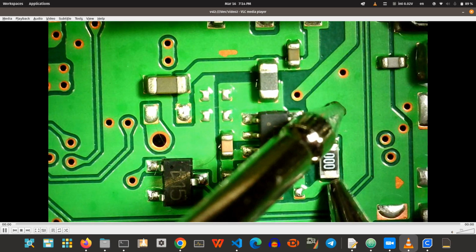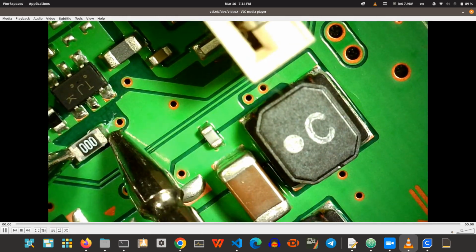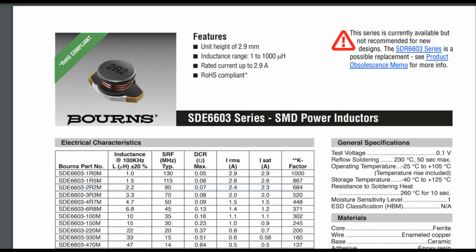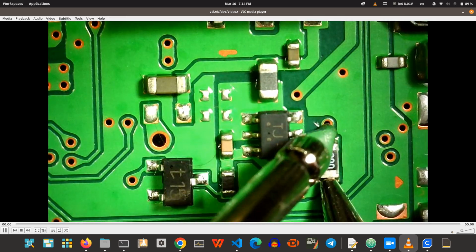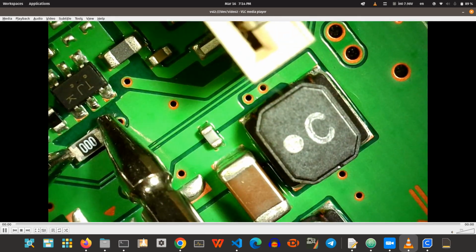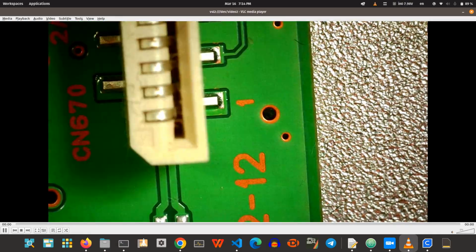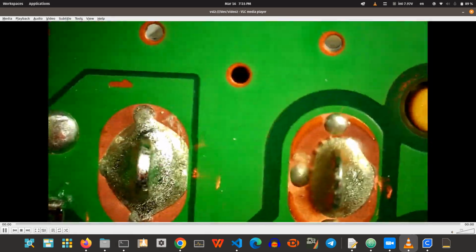We can see the MOSFET, we can see the driver and the 0 ohm resistor. So checking the resistor shows that it's fine. As you can see, it's not even easy to check the resistor. Yeah, look at the third column. It works on the frequency up to 130 megahertz. So this MOSFET is creating some heat, and the heat is basically transferred to the PCB through pins 1, 2, 5, and 6. You can see it on the datasheet here. I will show it now.